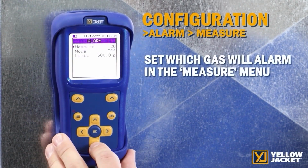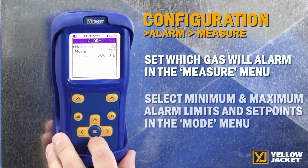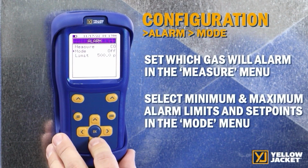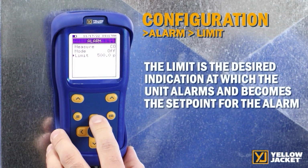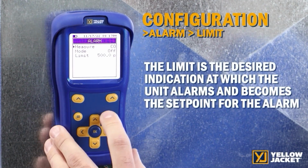Using Measure allows O2 or CO alarm. Using Mode allows the option of alarming at a minimum, a maximum, or turning the alarm off. The limit is the desired indication at which the unit alarms and is the set point for alarm.